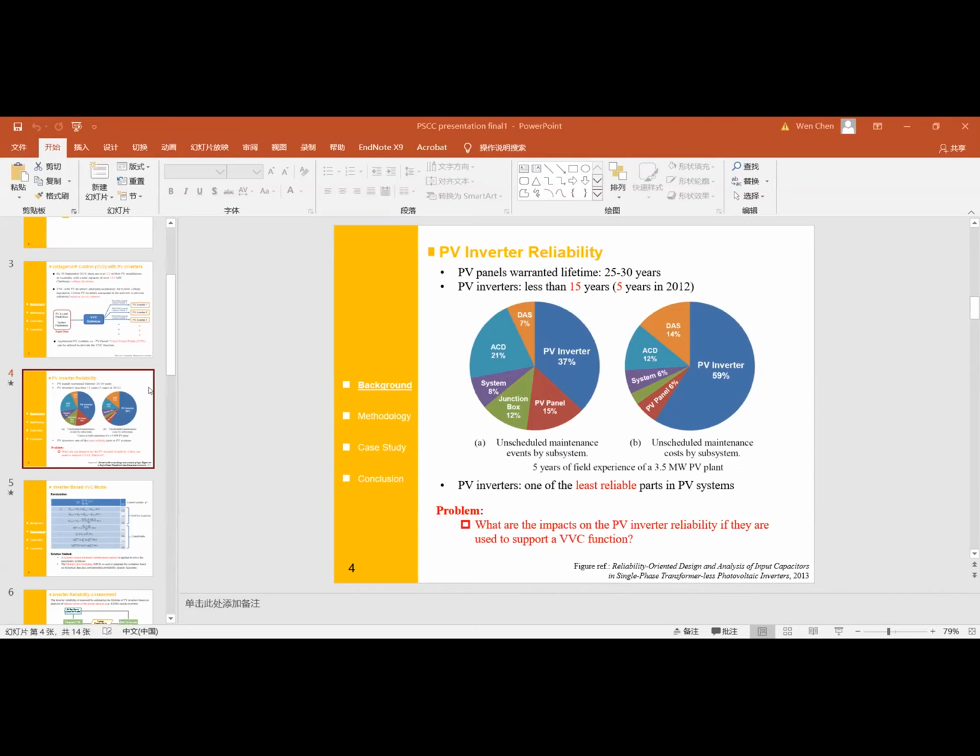For example, if the active power has a low value, we can provide some more reactive power to make the junction temperature less fluctuant. So that's the point, and that's the future trend for an optimized reactive power flow to prolong the inverter lifetime, I think. Okay. Thank you. Is there any further questions?